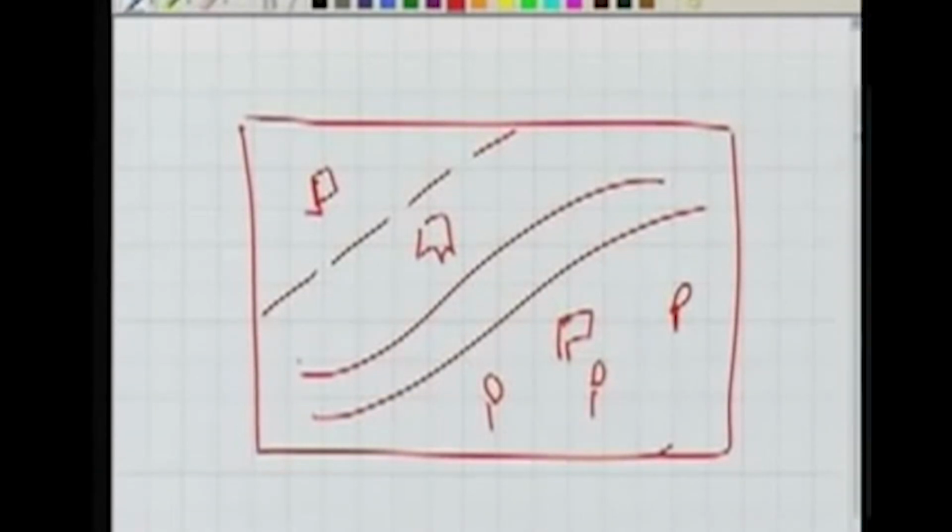And we also like to put these two control points A and B, because we can make use of these control points later on for some other purpose. So, this is how my map will look like. So, what we have seen is the entire process of making a map using chain and tape. There are many things which we need to look into. Number one, we haven't seen in detail this offset measurement.